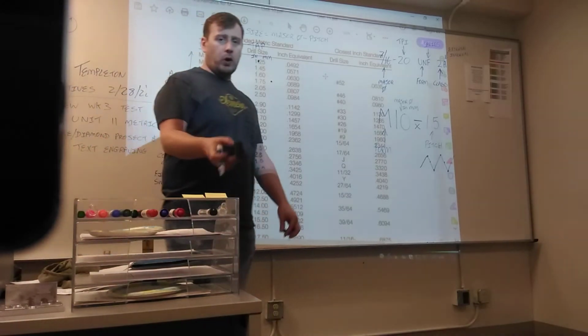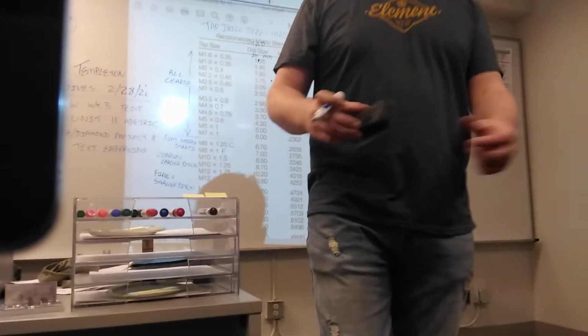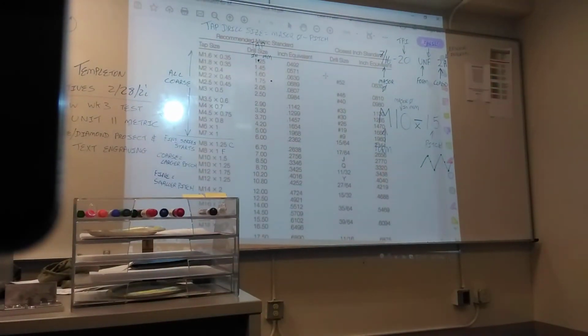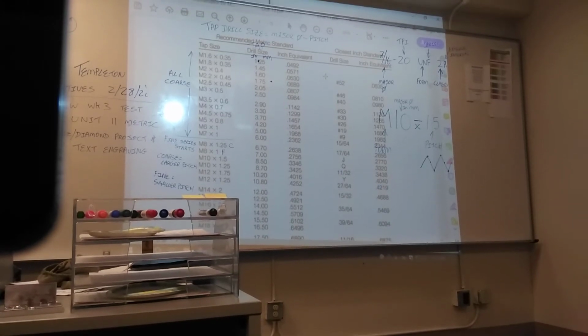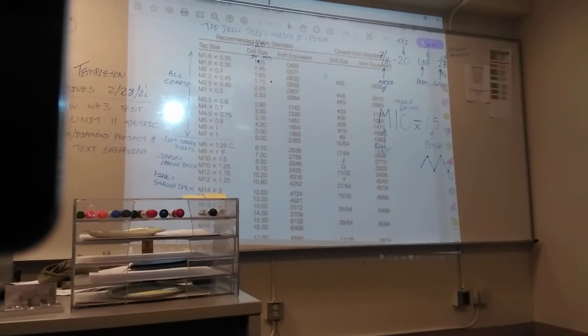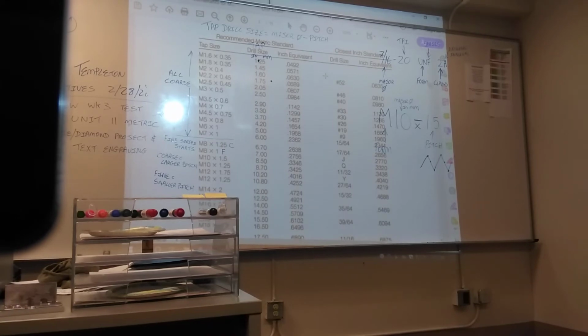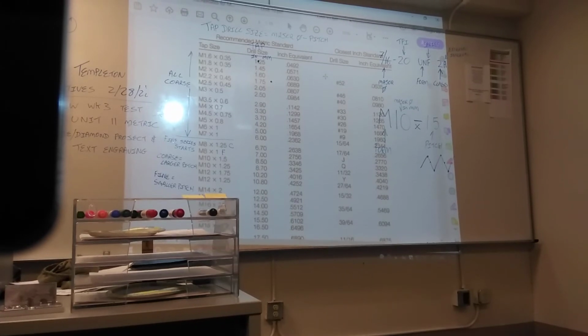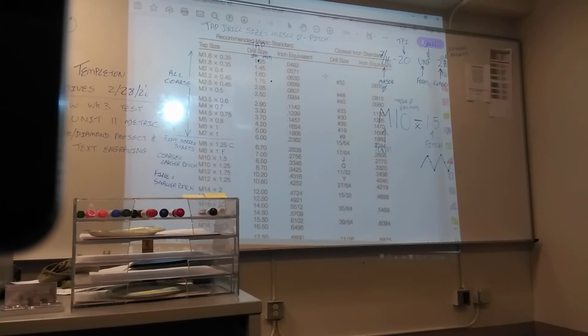Oh, okay. So if you put in your calculator 0.05 and divide by 25.4, how much different is that drill? 2,000ths. Less than the thickness of a piece of paper. So how much difference is that going to make to your thread? Not a lot. Virtually nothing. So that's why they just dropped down. If you see the difference here, ignore it. It's not going to make a difference.